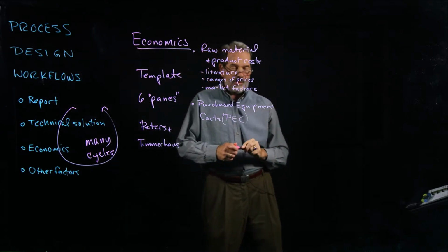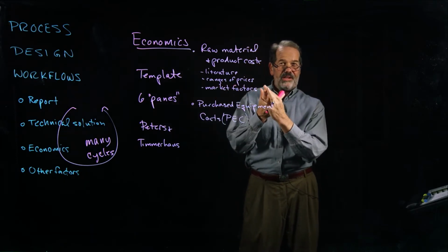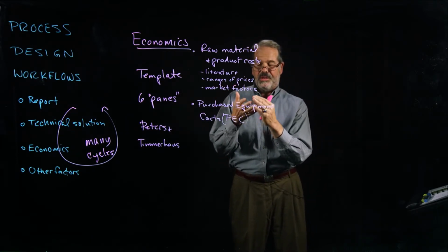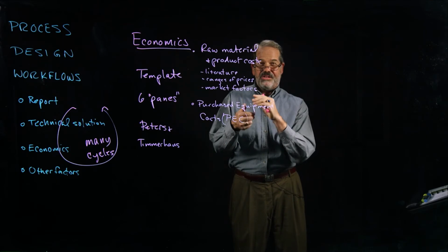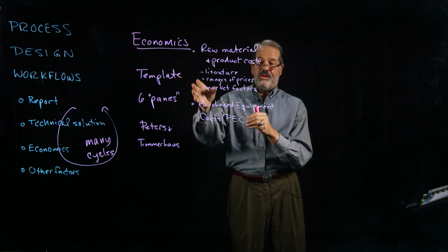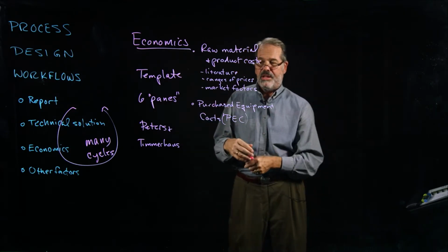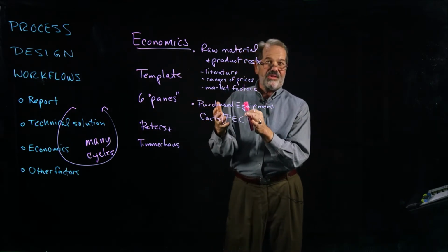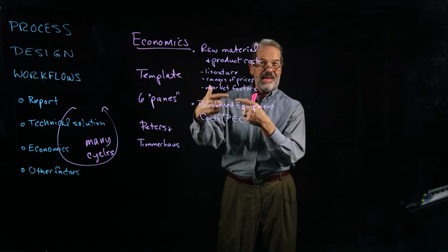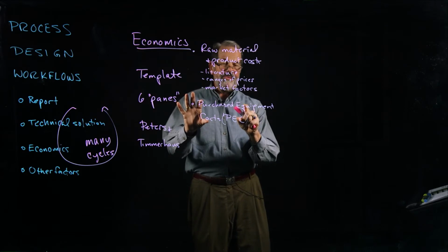So remember that we were talking about sizing the column, sizing a condenser, sizing a reboiler, sizing a reflux drum, sizing pumps, sizing storage tanks. All those elements are going to have a cost associated with them. There will be materials of construction that we have to consider which will impact the cost. So we need to put together a separate table for the equipment.